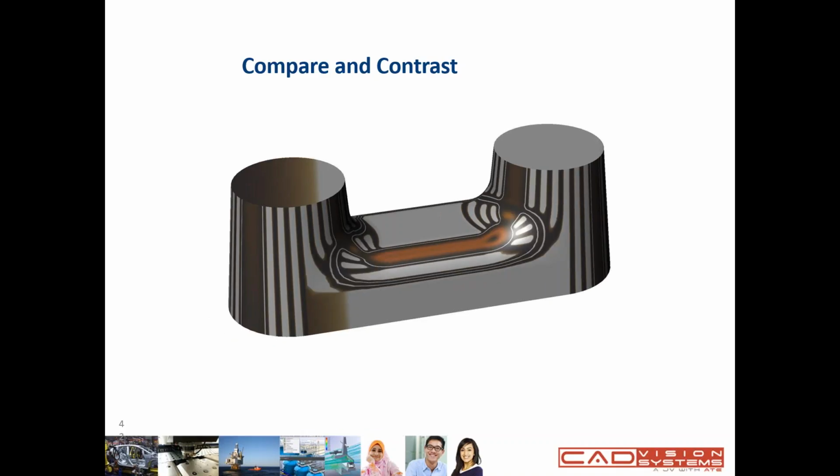But if you look at the next picture, that we repair the fillet using split line, and then we're using delete and fill to create a better fillet, more symmetry. Then you can see that the distribution is even now. It is symmetry, and it looks much better for the tangency control. So this is another standard problem that we will face when we do fillet. We always have sharp corner fillet, and then how we're going to solve it. All right.